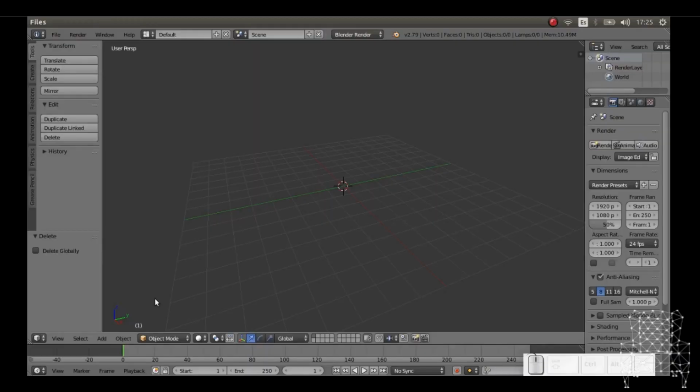Okay, so the first step for this is we have to adapt our simulation in a way that it is similar to the floor that we will use in the follow line in the real robot. So what we are going to do is create a model with a photograph of the floor as a texture, and that's it, and we will add that to the simulation.